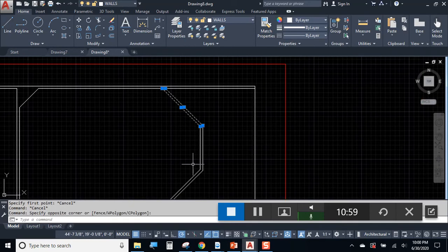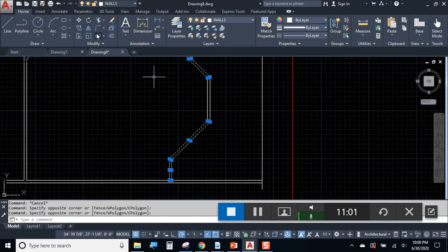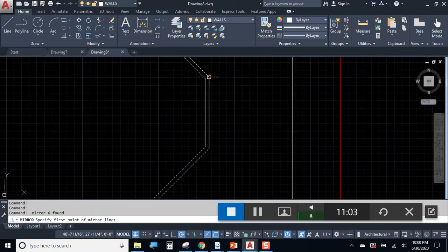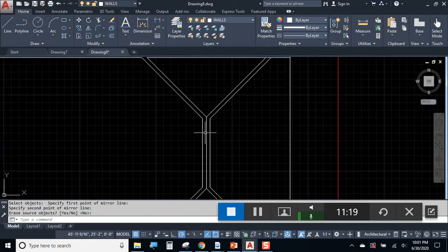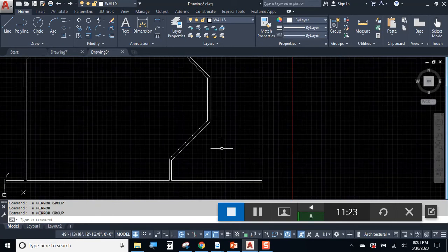If you offset this wall and these walls, and you offset them from the wrong place, like here, well, now you'd also be offsetting that line, mirroring that line. And what that does is it gives you 6-inch walls everywhere, but 12-inch walls here, and that's not good. So we're not going to do that.